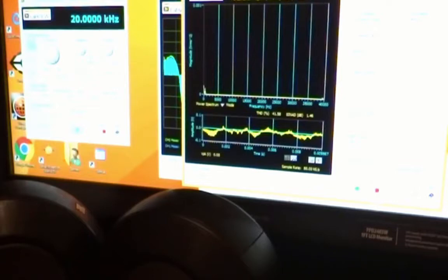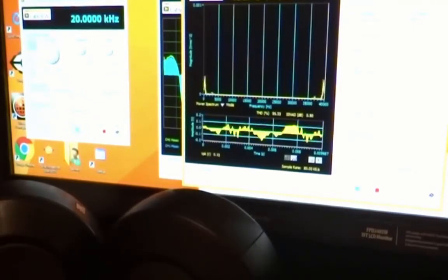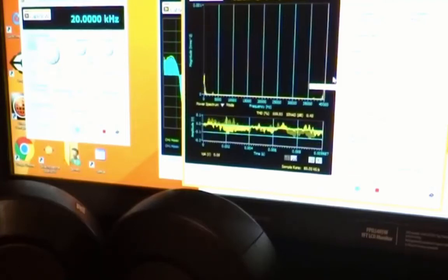So this is actually a slightly sloppy implementation. To really finish the process of getting the original signal, you would want to put a low-pass filter here to kill off this high-frequency copy that's hanging up there at 40 kilohertz. We didn't really bother with that here because of two reasons. One is, you as a human cannot hear the frequencies up here.